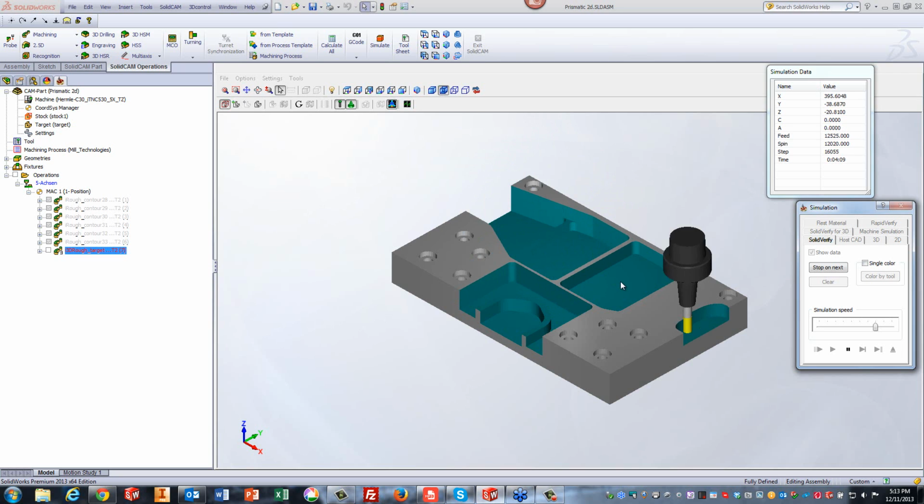Milling out each pocket exactly the way it should be done. Again, using the iMachining toolpath to do it. However, as you note, again, I did not have to do any kind of picking up the depths as far as the pockets themselves. Yes, I did pick the depth over here because I already knew that I really don't have to go all the way down over there, and it's not going to go down over there anyway, so I just clicked it over here to save some calculation time. But in any case, I only did one operation instead of 6 operations, and this was done by using iMachining 3D. Very simple way to work.